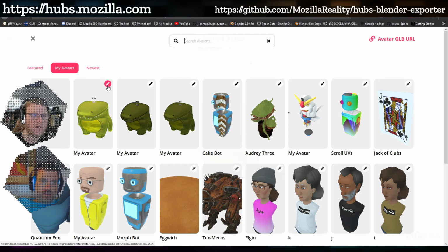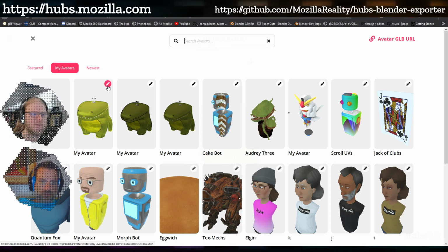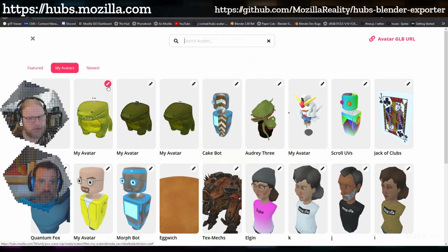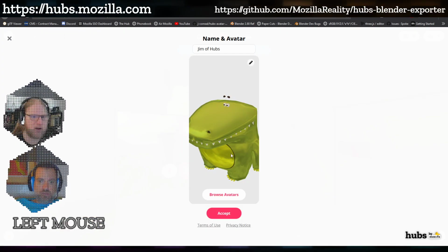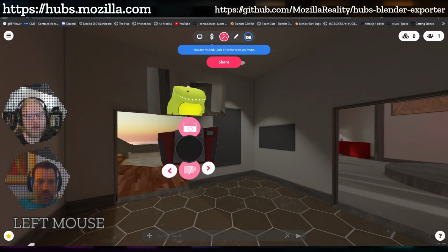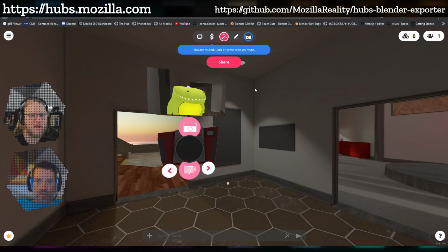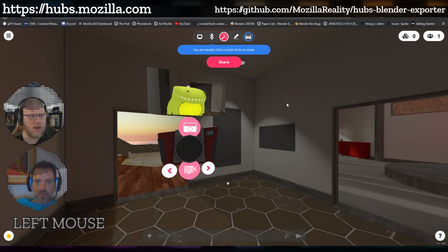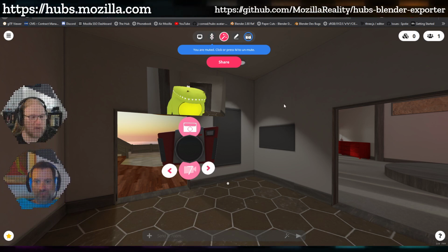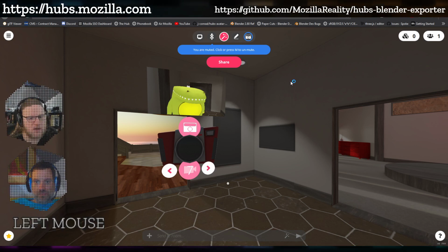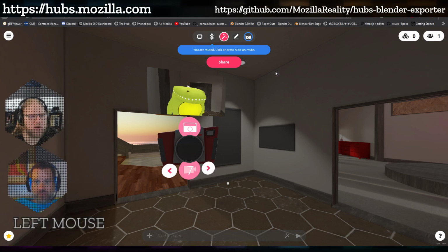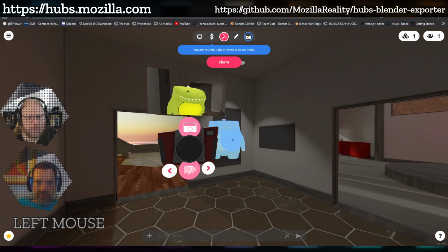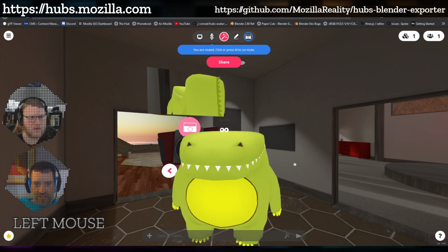What you can also do for testing this animation specifically is drag the GLTF into Hubs just to preview it. Oh, that's true. So as you're iterating over it, you can do that sort of thing, if it's not something that you actually need to be in an avatar to test. That's really helpful to know. The voice feedback stuff obviously is not going to work unless you're in the avatar, because it's only checking for voice if you're using it as an avatar. But for things like animation, if I just drag it into this window, it'll show the animation play by default.